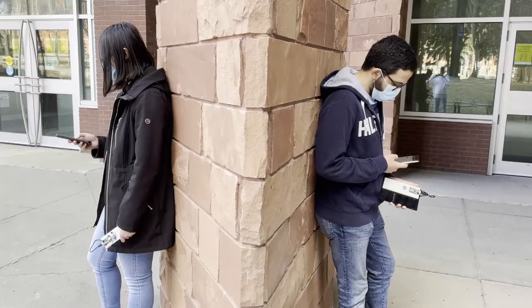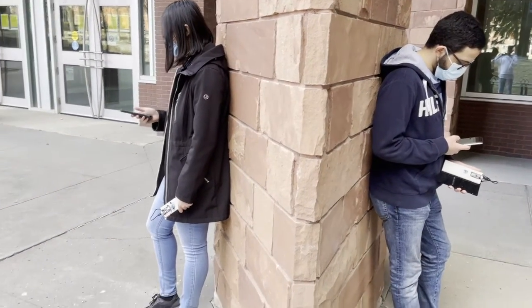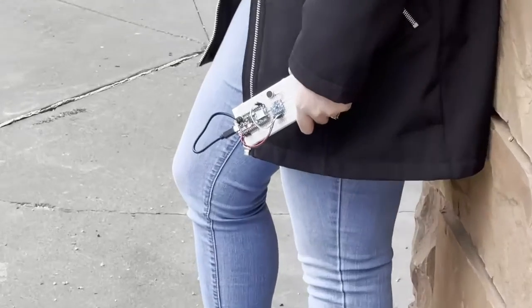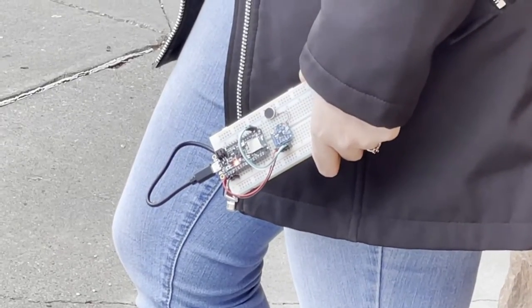Here, Amy and Ibrahim are standing less than 2 meters away from each other. However, they're still following safety precautions since they are separated by a wall. The wall introduces noise to the device's beacon and diminishes the BLE received signal strength indicator, or the RSSI value. This causes the distance measured by the device to be greater than 2 meters. Therefore, the Cody system does not alert the haptic devices to vibrate, which is the desired outcome.